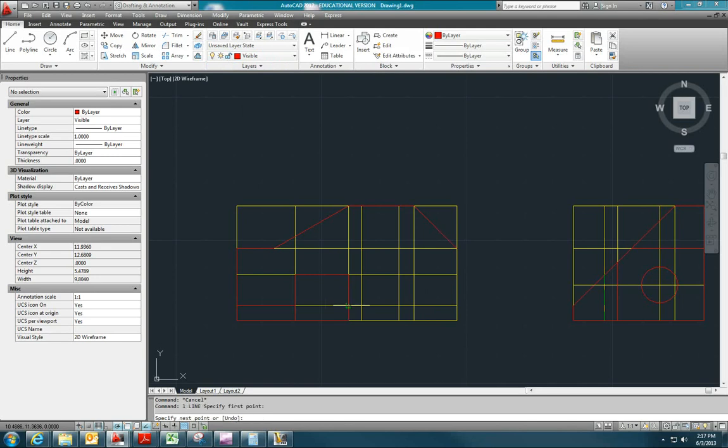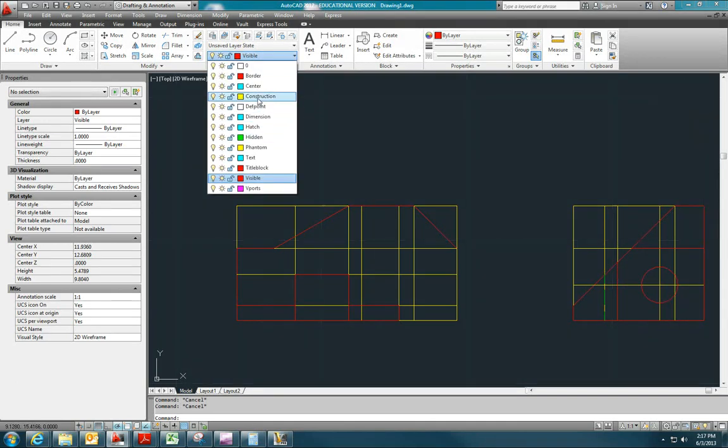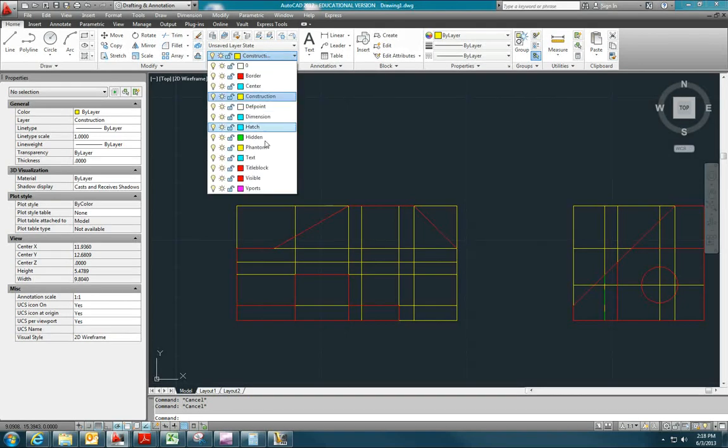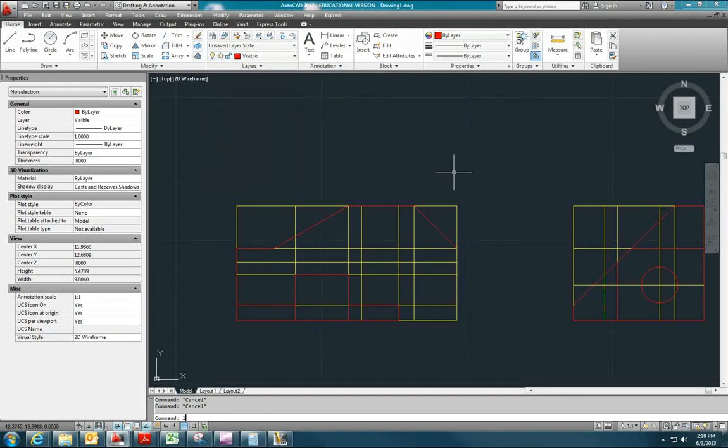So now we have this area here that needs to be created, and then the part that is recessed back by 0.76 goes up to this line. So let me take that line and I will draw it all the way across. And go back to my visible layer. And now I hope you're seeing how these views work together.